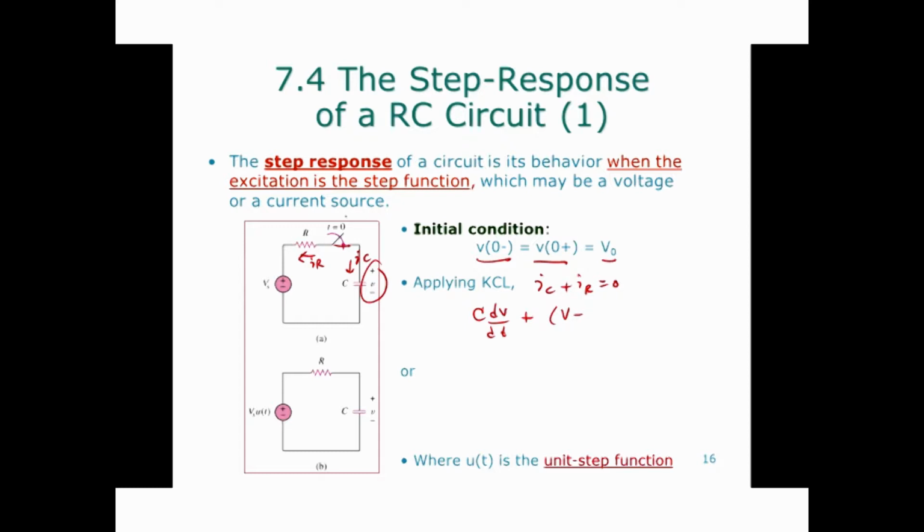According to the nodal equation, IR is going to be the voltage V of the capacitor minus Vs, over R. To really improve the mathematical model, I might write Vs times u(t), because for t less than 0, that thing is 0, and for t greater than 0, it's on. Some of these things are a little hand wavy. The step functions are nice for mathematical purity, I suppose, but physically, it's just a switch turning on.